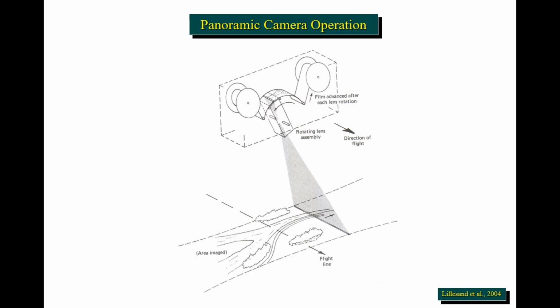It does not yield very rigid geometry, and again, we're going to have widely varying scale as we go from the image portion of the terrain that is along the flight line versus as we proceed along in either direction toward the horizon. But measuring and mapping are still potentially possible, though, if we are utilizing the required equipment.